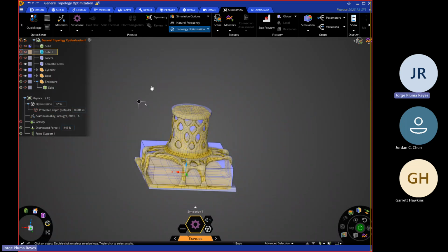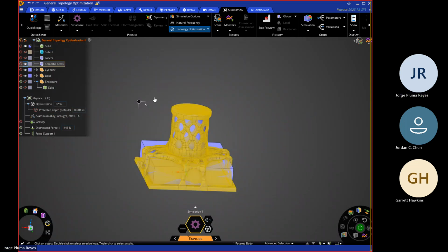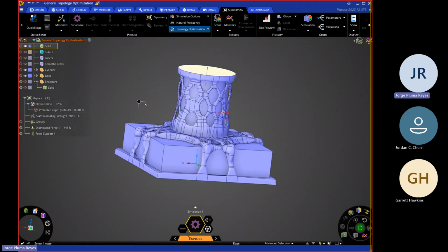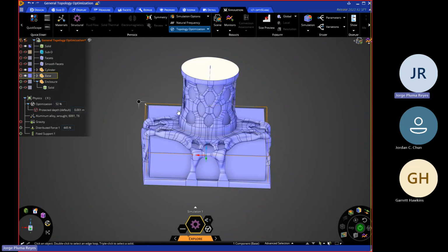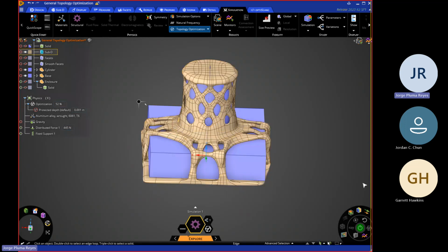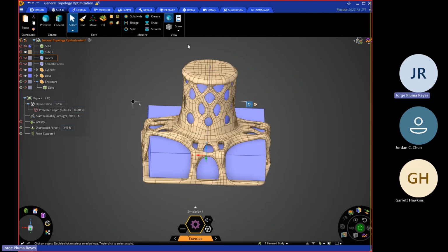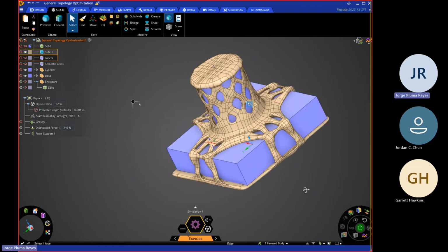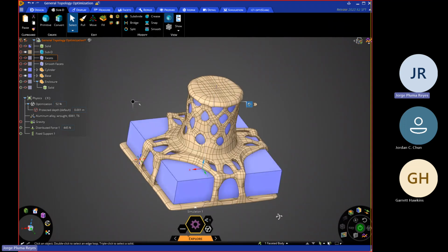And you can also create a solid from it, which would be this example here, and it'll just be a solid part that you can modify with surfaces here. And the third and probably coolest feature here in Discovery is that you can convert it into a sub-D model. You would just click on your facets body and go to our sub-D tab and click on convert. From here, you end up with this subdimensional model, which is very